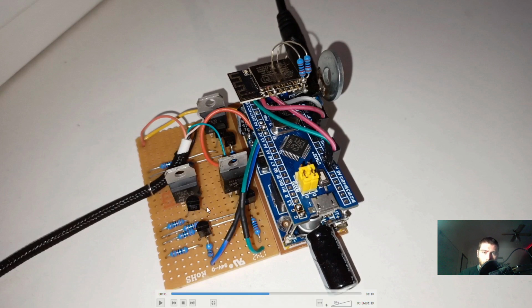On the other hand, these step-down modules that use a coil and the switching component are very efficient, so they don't need any extra cooler. And these MOSFETs can switch several dozens of amps. Therefore, as they are switching just a few amps, they don't need any cooler either. So this is quite a good solution.